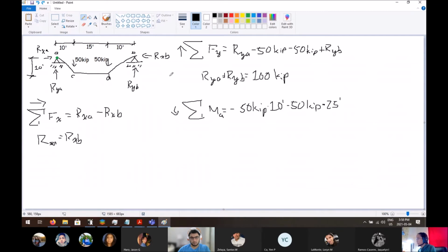And then we have Rxb pointing directly at A. We're going to extend the vector into a line. You see how it goes directly through A, 0 feet away from A, so we're not going to include it. And then we have RYB, that's going counterclockwise, so finally a positive value. And how far away is that? 10 plus 10 plus 15, that would be 35 feet.